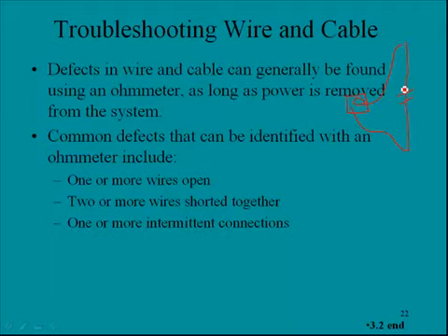An old electrician's trick: sometimes if you have a wall outlet, and let's pretend that for whatever reason voltage is not getting to this outlet, there will be a circuit breaker associated with it. Usually a technician would go to the circuit breaker and measure the voltage there to ensure that voltage is in fact there, because maybe the circuit breaker is popped. But these wires will go to this particular circuit.